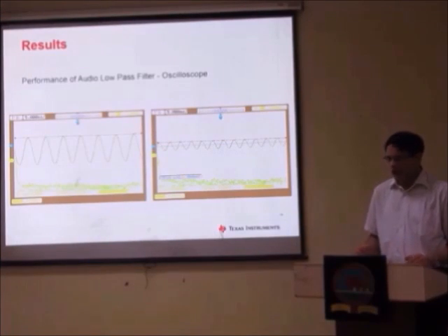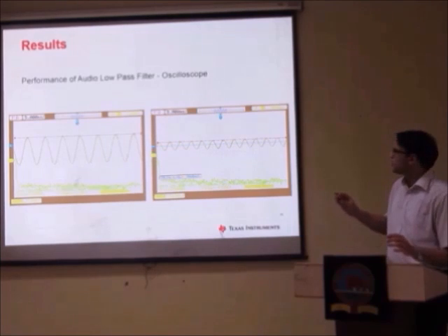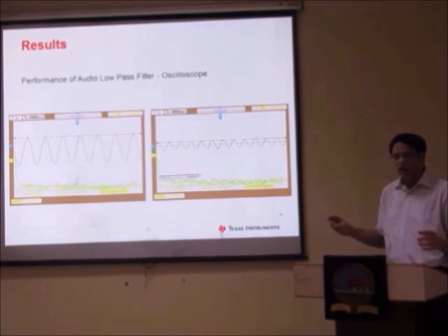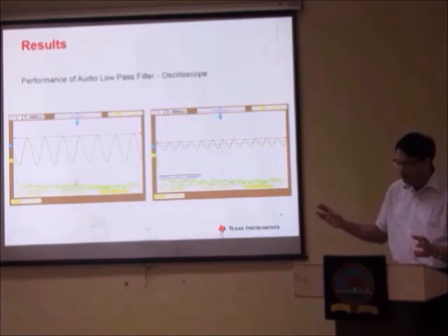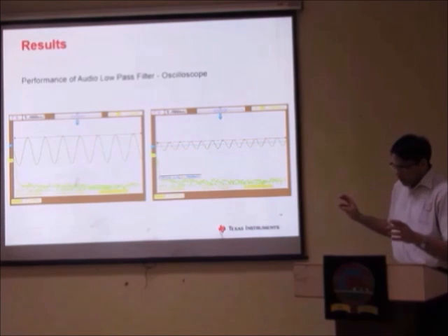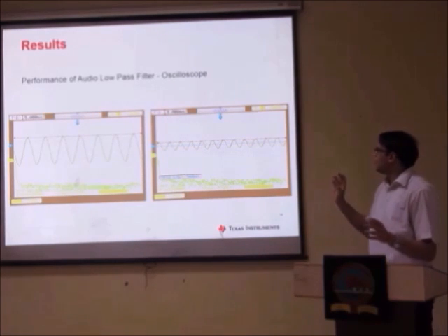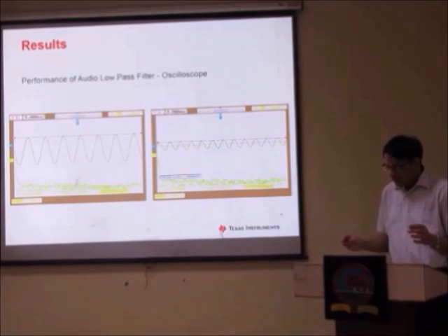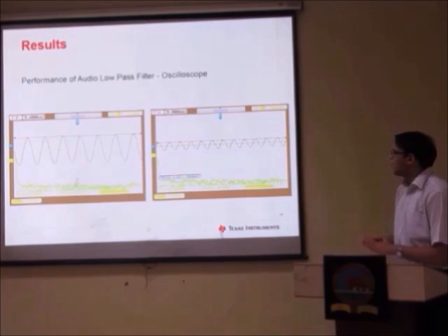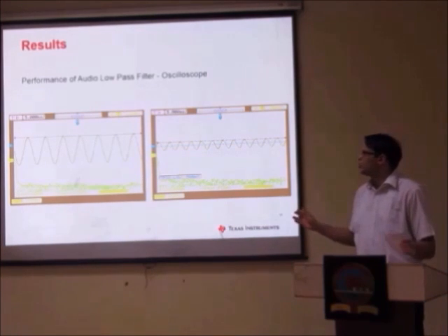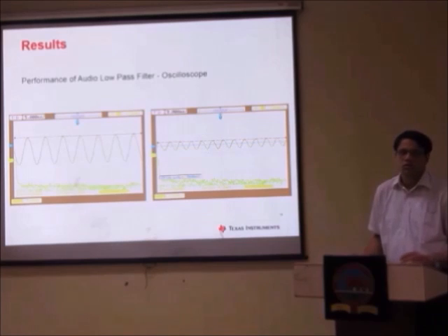Here are actual performance results of the UAF42 filter grabbed on a DSO in the lab for 100 Hz and 120 Hz. There is virtually no output above 1 kHz. The tactile vibration feedback mechanism adds a lot of realism to our train simulator project.